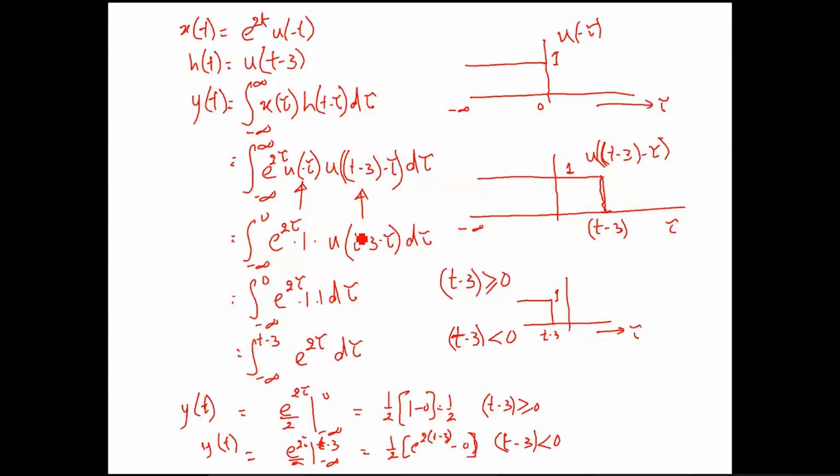The complexity lies in finding out what is the effect of these step signals. Specifically, this one at times confuses people about how this whole thing is going to look. Remember that whenever you have this u step signal, it will have value equal to 0 within a certain range and value 1 within a certain range. For the range where the step signal is 0, we just discard that because it will make the whole product 0. And the range where it is valued at 1 is the one which is going to give us our limits.